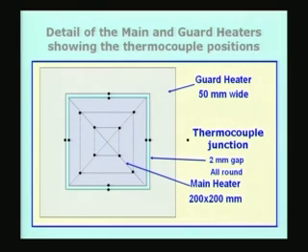So, on each side I am going to have several thermocouple junctions like this, and then I am going to average them. In fact, I can do the averaging by simply connecting all of them, as we have seen earlier. If you connect them all in parallel, you will get the average value of the temperature, because we are expecting that the temperature is more or less the same, uniform throughout, but there may be small perturbations, small changes. So, we would like to find out what is the mean temperature on this side, because for heat transfer calculation I need the mean temperature on this surface.